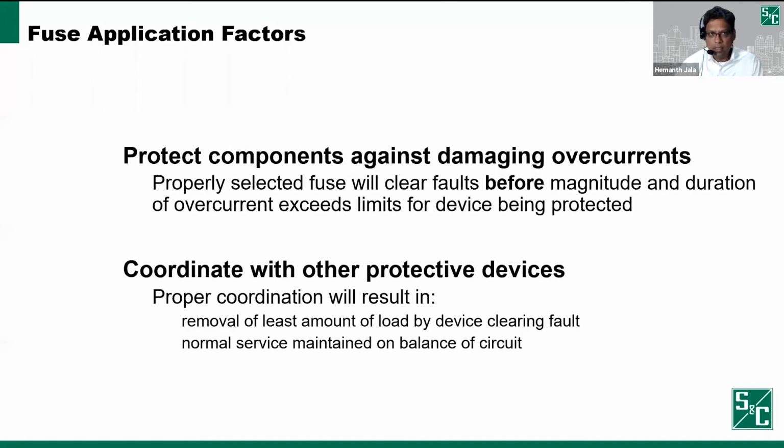These are the general guidelines when you're picking a fuse and the application factors. You want to protect the components against damaging overcurrents. Remember that first goal: protect against damage from overcurrents. You want to make sure that the fuse you select will clear the faults before they reach a harmful level that would damage your equipment.